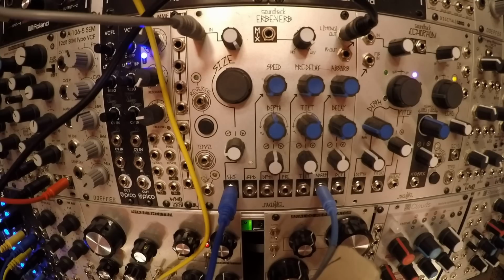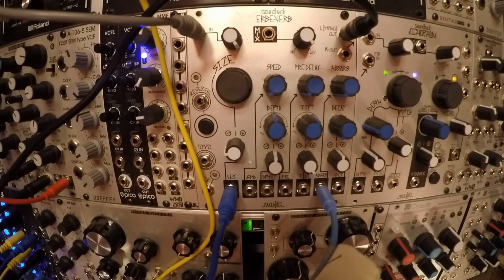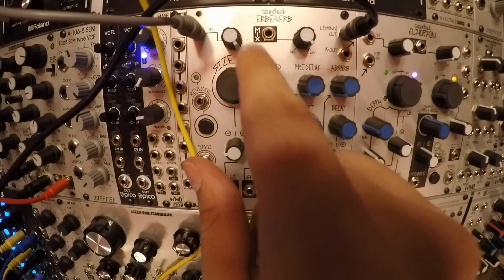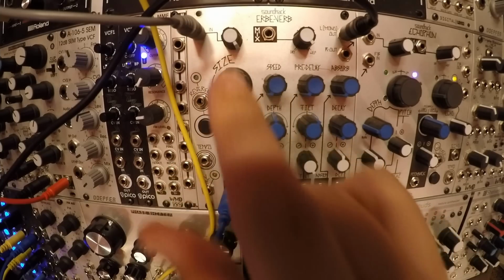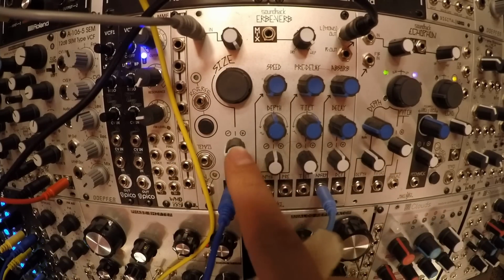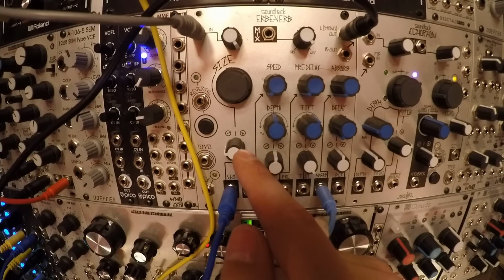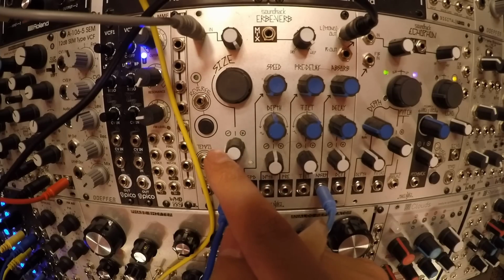Normally, I would FM this parameter, and by normally, I mean the most times that I mess around with this particular thing, actually just make sure that I'm right here. This is out, that's 5 and 6, so that makes this, yep, this is the offset. So, what that means is that instead of this being FM'd, it's being modulated, like straight position. And this knob is determining the intensity of it. This is also an attenuator, or actually what's referred to as an attenuverter, because it can also be a phase inverter. The center position is actually off, and there's a positive and negative in the parameter's motion.